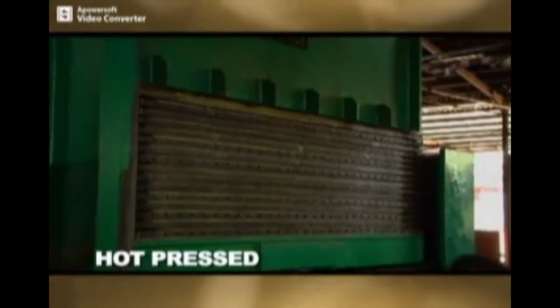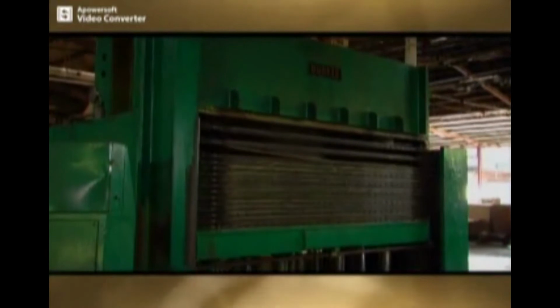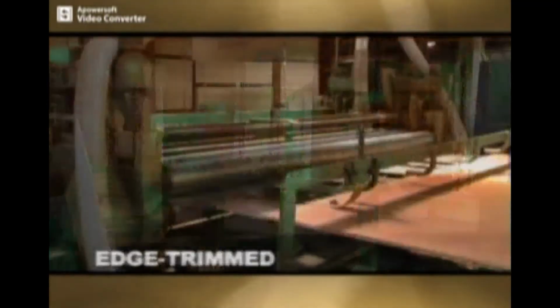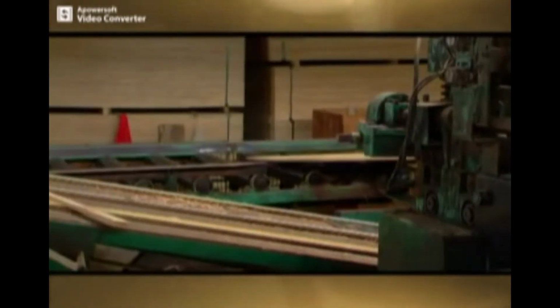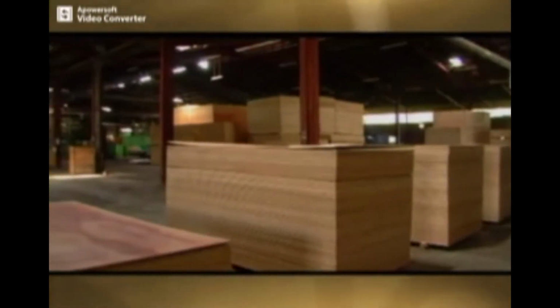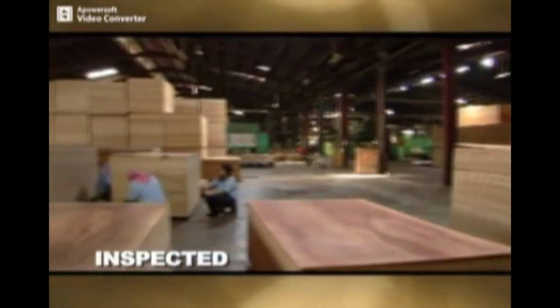Finally, the pre-formed panels are fed into the hot press to complete the lamination process under preset conditions of high pressure and high temperature. The palm plywood panel is then edge trimmed to the required size and then sanded for a smooth surface finish. In the final process, the panels are inspected, touched up where necessary, accordingly graded, then packed and bundled for distribution.